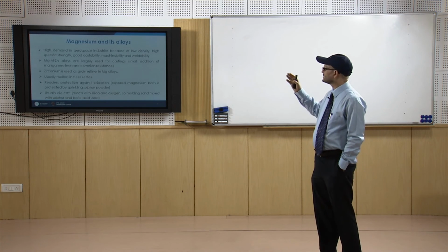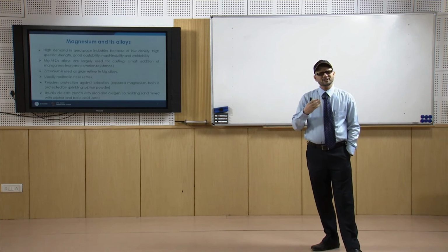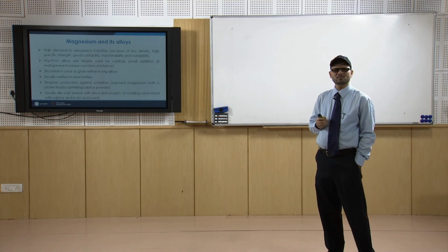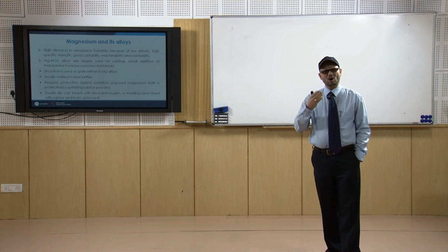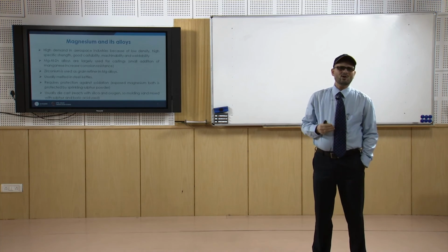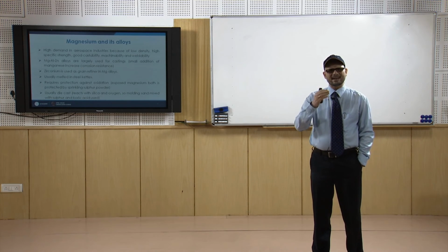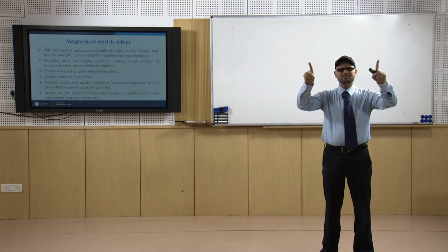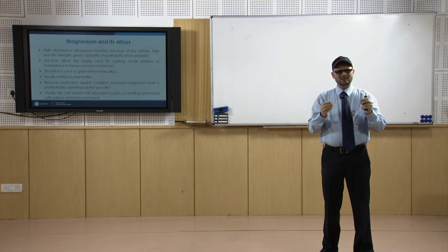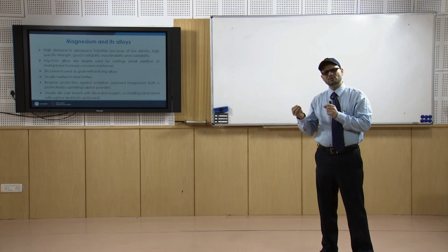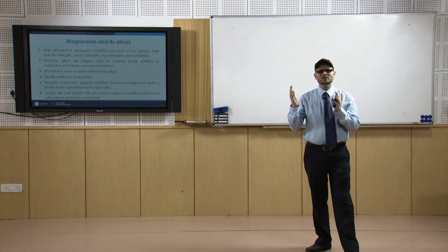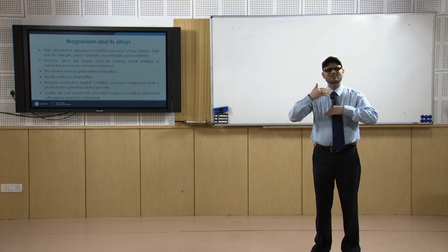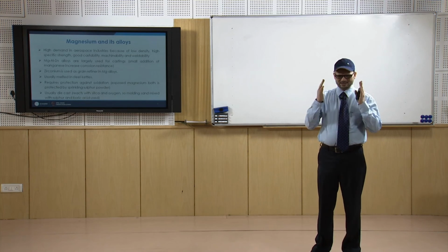So, in a nutshell, we have other kind of materials, non-ferrous materials, like you have zinc which has quite low melting point. If you talk about the copper, copper is alloyed with a lot of alloying elements like aluminum, like zinc. So, with zinc you get the brass. If you look at the phase diagrams, we can come to know that with copper when alloyed with zinc maybe up to about 55-57% you have the cubic FCC structure. So, it is alloyed to a larger percentage with zinc, which has a very good property. So, that is very much used.